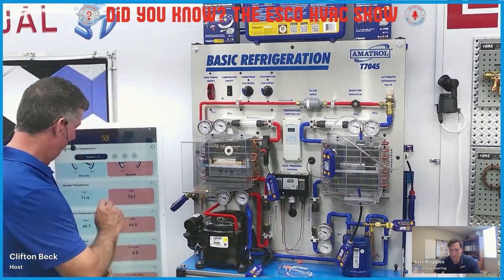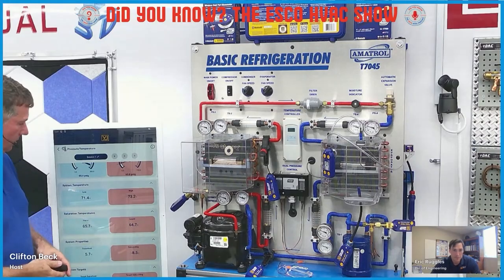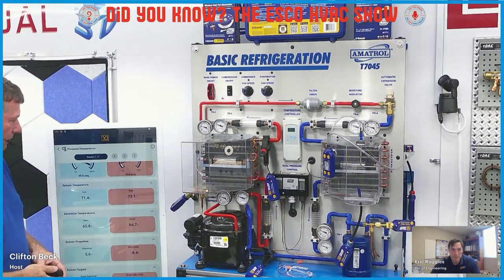Yeah, you should just need to push it up. Yeah. Now we have pressures and temperatures. Looks like your system's equalized, so it's not operating right. So temperature's the same, pressures, superheating, subcooling don't really tell you anything at the moment because it's not operating.